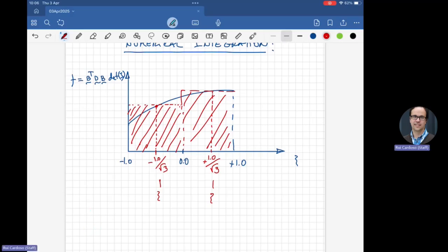So what I do is I calculate my BT at C integration point 1, multiplied by my material matrix D, and my matrix B. So I evaluate my function at this point, I calculate my determinant of Jacobian at this point I, and I multiply this by a weight, which, if you want, is the width of this thing. Okay.